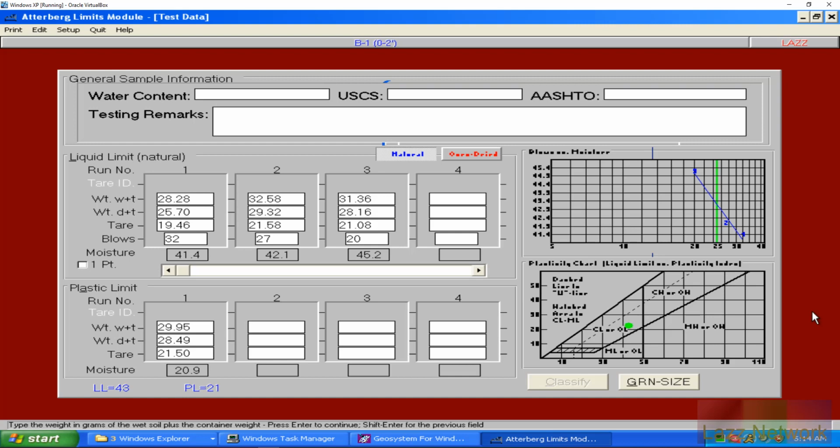So the thing is, when it comes to classifying a soil, the bare bone basics of classifying soils overall is you need a wash done on it, and a wash is exactly what it sounds like. It's washing soil. There's so many different ways and methods that you can wash soil. It mostly depends if you're going to use basic dish soap, or if you're going to use chemical means, which is sodium hexametaphosphate, to clean your soil.